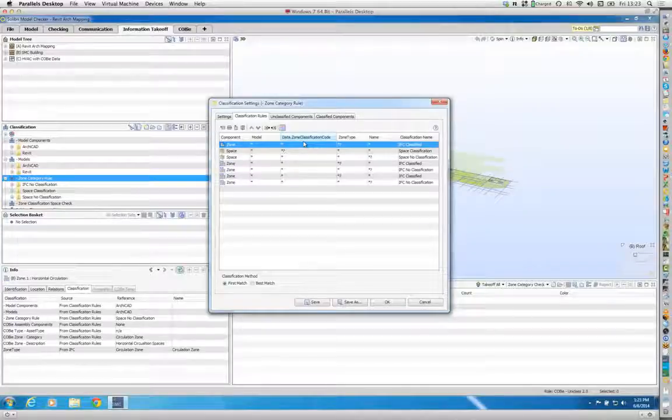And then you have zone classification code, which is another parameter that you can apply to each space. And then you also have one called zone description. They're special fields in parameters inside Revit, which give certain functionality. So the zone name and the zone description export out correctly and will drive the functionality in the right way. The zone classification code doesn't seem to quite work yet, so I've got to have a word with Angel at Autodesk to see if we can sort that out.